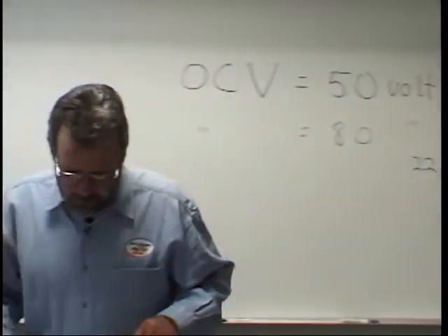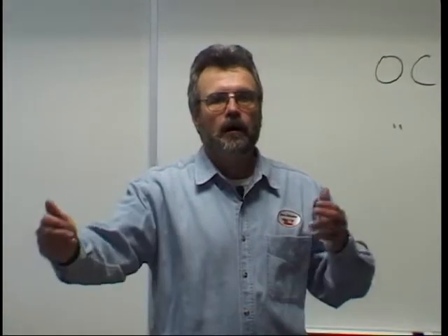Okay, let's go back to your book. Next page, 761, current controls. There is no current adjustment dial on a constant voltage unit. Current is adjusted by the wire feed speed setting on the wire drive unit, which is what I mentioned earlier. As you increase your wire feed speed, the power supply automatically increases amperage to burn off, melt that additional mass, that additional material.